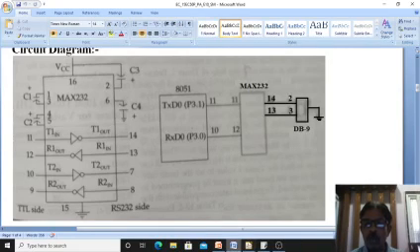So now let us begin the experiment, that is, designing the PCB layout for this experiment. Once again, quickly, let us see the requirements. One MAX232 IC, one DB9 connector, one 2 pin connector for connecting from the microcontroller, and one more 2 pin connector for connecting VCC and ground. Then the components required are VCC, ground, and associated power flag, and 4 capacitors. These are the components I require.